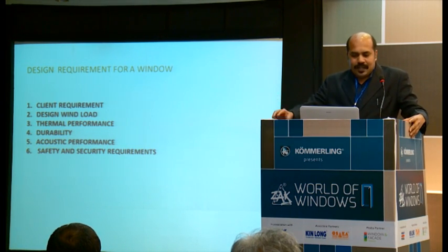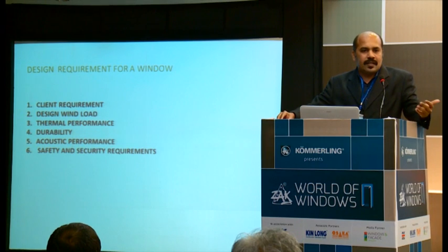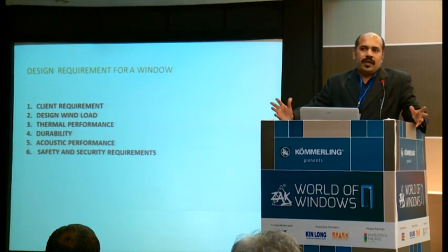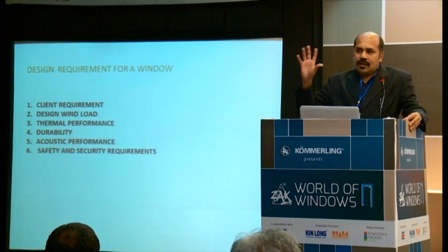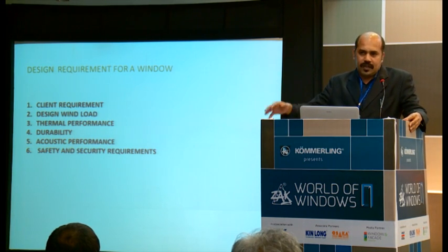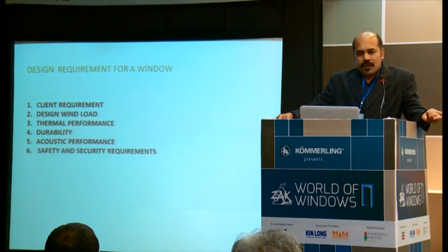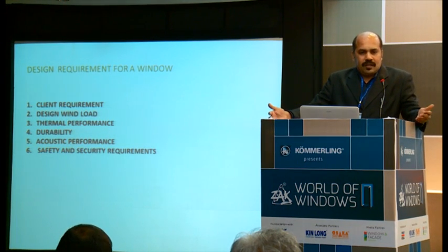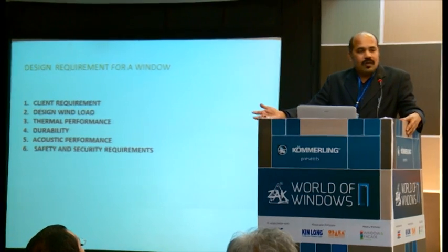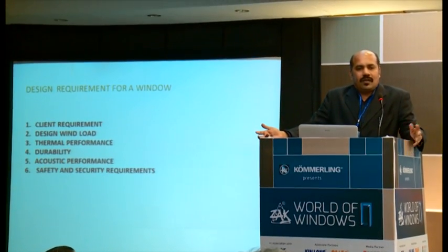The second point is, as a consultant, whenever a client has got a plot and an architect designs a building and gives a concept, the first thing is to understand the loading requirements. You call any of the system providers or contractors, and they need to give calculations of what the actual wind load is. You may over-design it or under-design it.